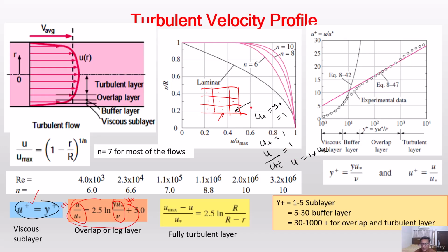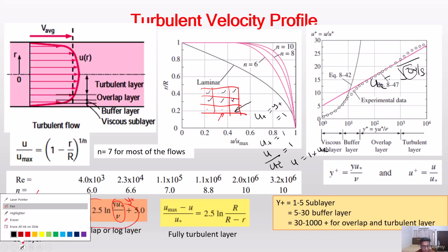You can find the friction velocity, which is given by the square root of the wall shear stress divided by density. Once you find this value, you can find the velocity from there, and the tau wall comes from the wall conditions. We can now put the velocities at these different locations, and these velocities may be different because the y plus may be different, and maybe the friction velocity is different. With the friction velocity different, y plus will be different, and so u is different. Once we provide the properties here, these points will be solved numerically by the solver. So that's why this is a very important thing to do.